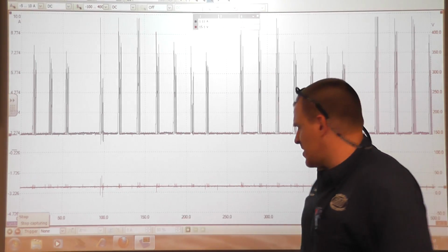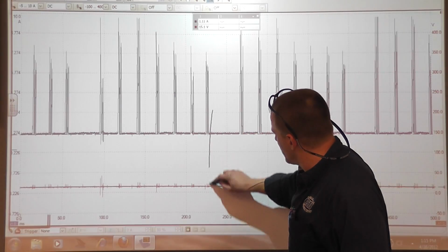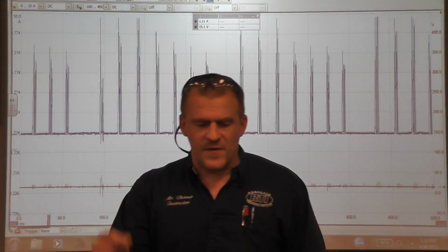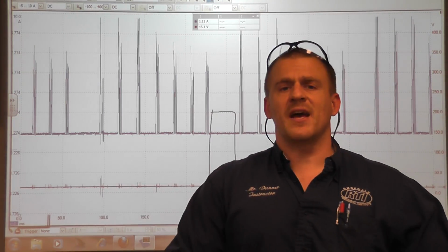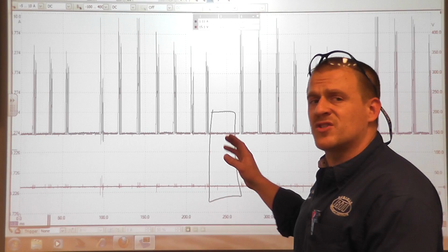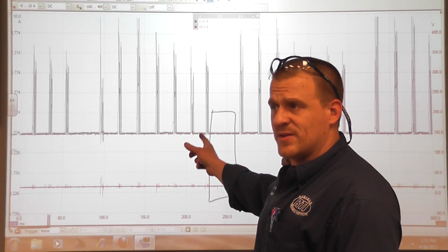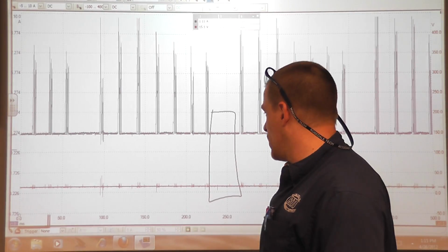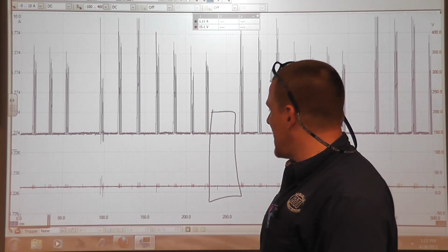One other thing to consider is this circuit right here. If this driver, in fact, did get damaged and got cooked, is it a possibility that cylinder number 6 ignition coil shorted out and caused this condition? So when it comes time to, let's say, replacing this computer, you can be sure that we better be doing some checks on this cylinder number 6 ignition system, or this cylinder number 6 ignition coil. We can do some ohm tests on it.